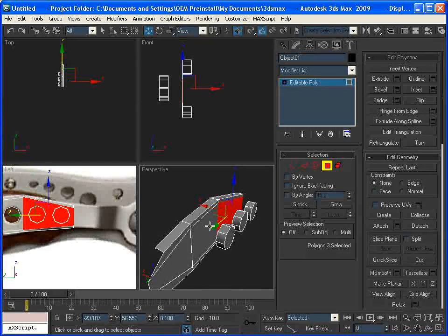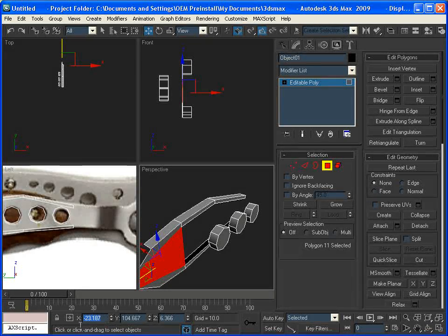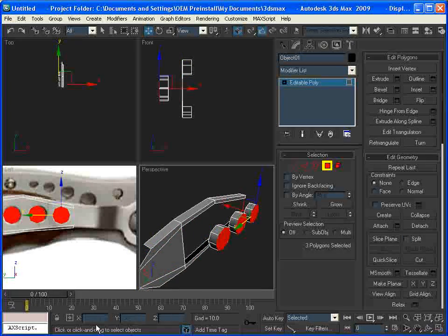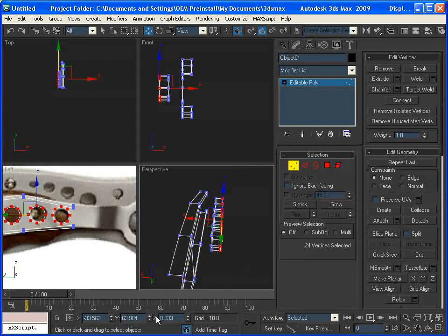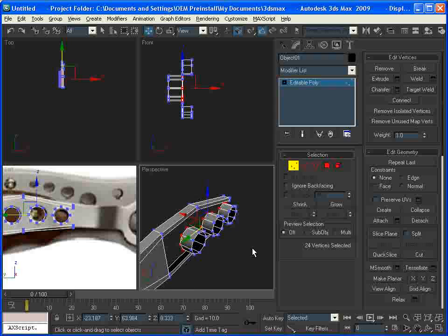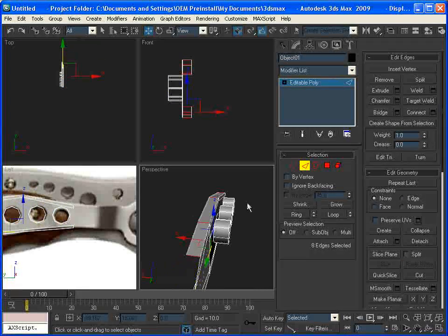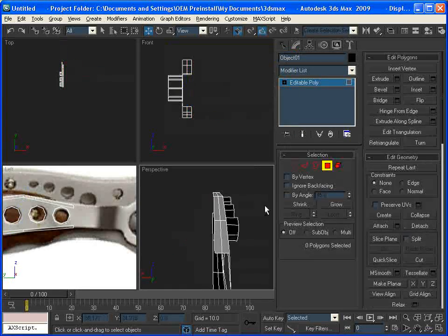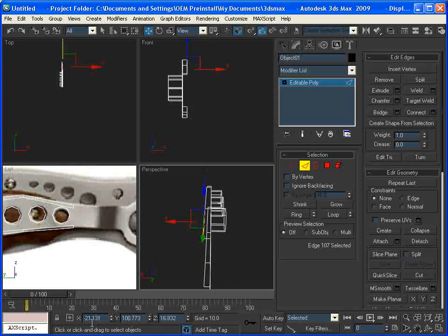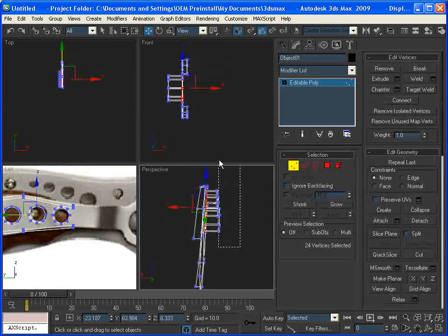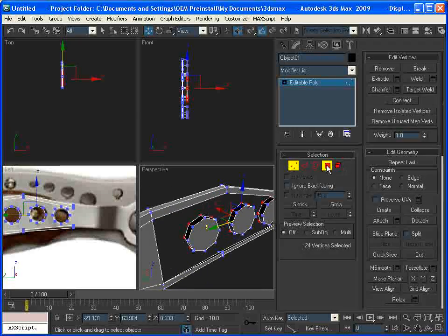Delete these faces. Get the x-coordinate of them, of the faces, and then move these in. Oops. I have to select vertices so we can actually do this. Move them in. Alright. Now we're also going to add a symmetry edge here. This is where it starts getting crazy. Add a symmetry edge in this part of the model that we cut off the part of the other model. Get its x-coordinate and move these there. Okay. Yeah, this will work.